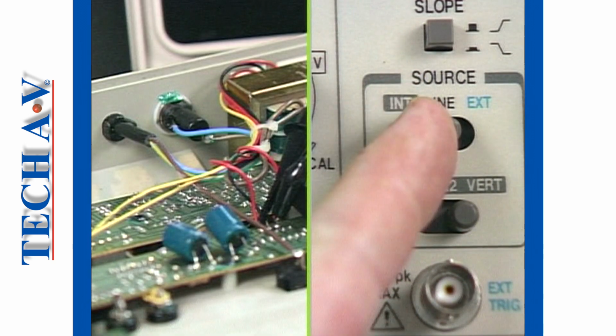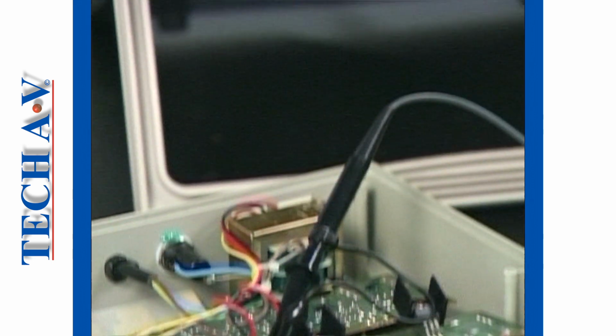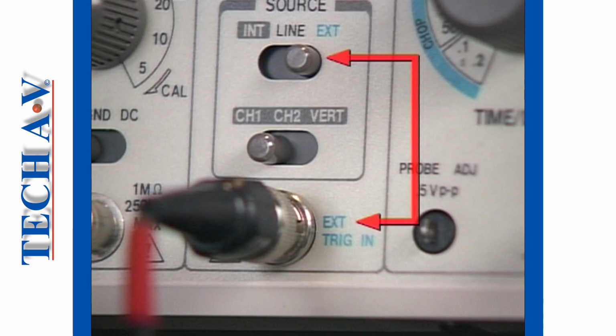Selecting line causes the time base to run at the power line or mains frequency, and is useful when analyzing power control equipment such as DC and AC drive systems, whose circuitry is all mains frequency related. The external position simply means that the trigger signal is derived from an external source and fed to the scope via an external input BNC connector.